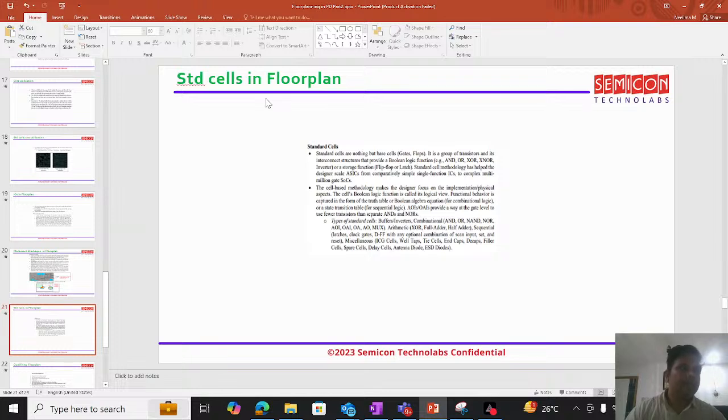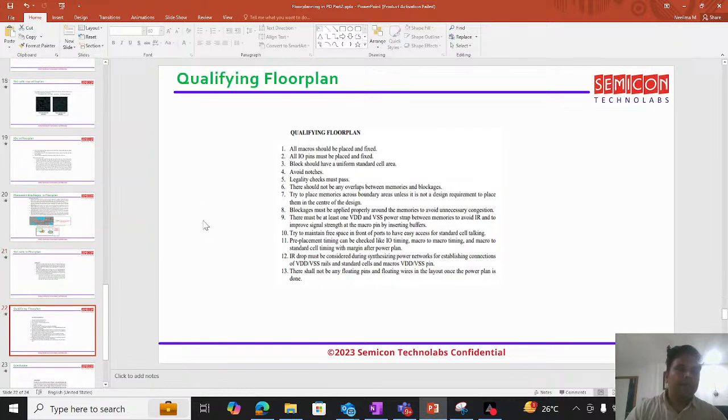Okay, these are all bigger cells which we call macros because they occupy multiple site rows. All right. Now let's see how we qualify a floor plan. Following all these guidelines, control parameters, limitations, calculations, all the different types of placement blockages and routing blockages, once the floor plan is done, how do we qualify the floor plan to take it forward?